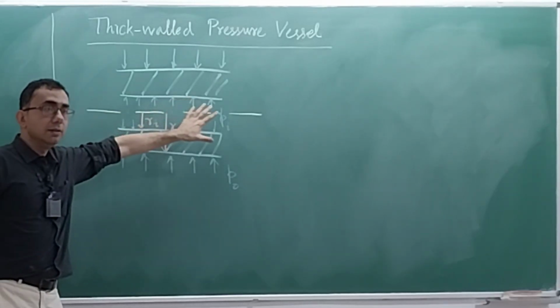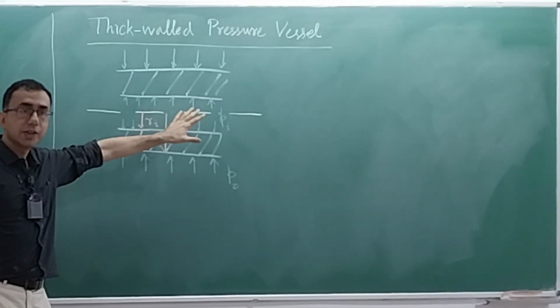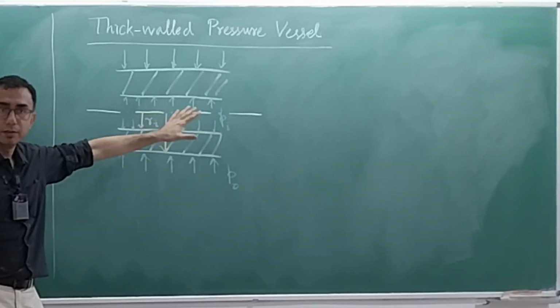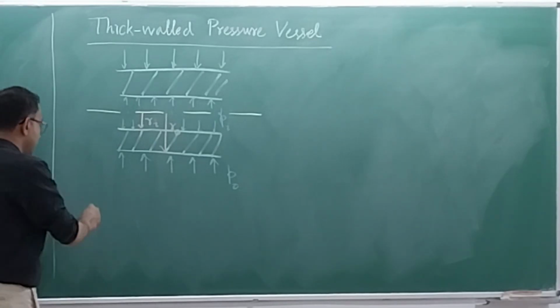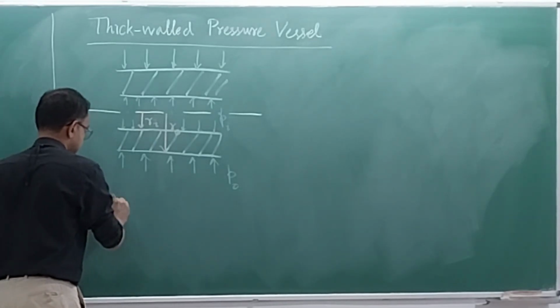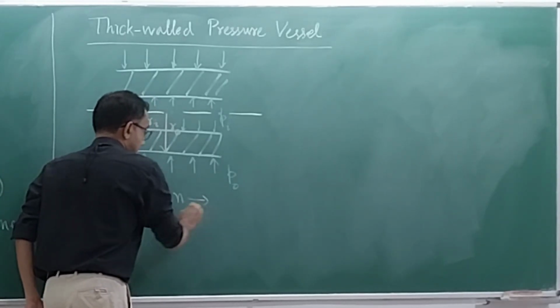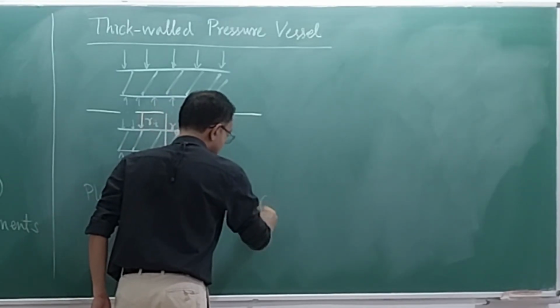So tell me, here is plane strain valid? There is no variation of the pressure in the z direction. There is no force in the z direction. So plane strain is valid. Okay, so this is a condition of plane strain. That means that the del z of anything will be equal to 0.